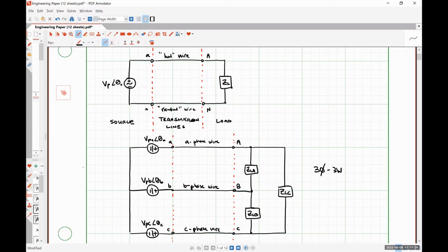So they experience a large surge of energy, which causes them to sort of jerk start, and then they smooth out to their normal speed. Well, with a variable frequency drive, you can start them off slow and continuously bring them up to their speed without that herky jerkiness and all that kind of good stuff. That's kind of beyond the scope of this class, but it is a thing that happens.